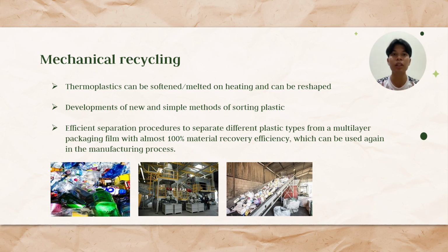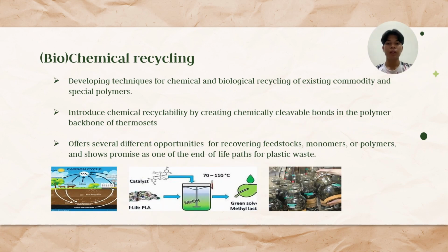For example, special adhesives are being developed based on reversible cross-linking and the cross-linking chemistry occurring at different temperatures to provide easy delamination of the plastic layers after use, simply by heating at a particular temperature before they can be mechanically recycled. The second recycling strategy that we have is biochemical recycling.